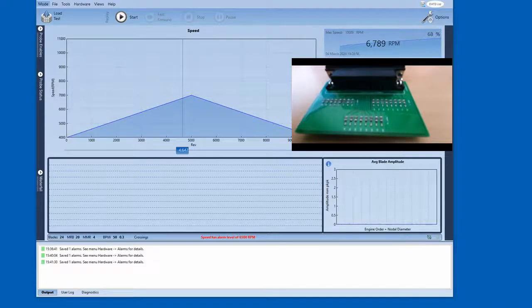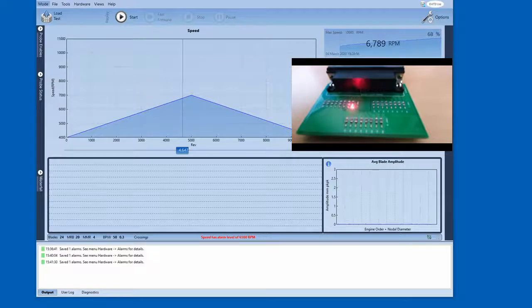You have, top left, the watchdog, or the handshake, or whatever you want to call it, to prove that the hardware is still alive. So if you've got a supervisory system this is plugged into, it should expect that. If it doesn't see the watchdog on bit 0 on the top left port, then it knows something's wrong. It's either not connected or something's not switched on, so it knows that the system's not primed and not running. Okay, it's just a sanity check and a bit of a safety feature.